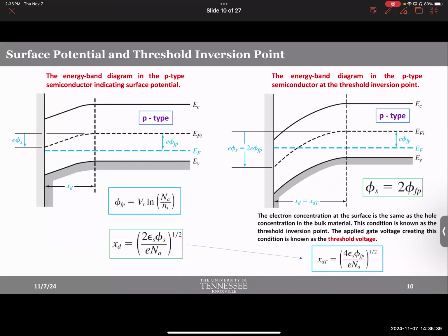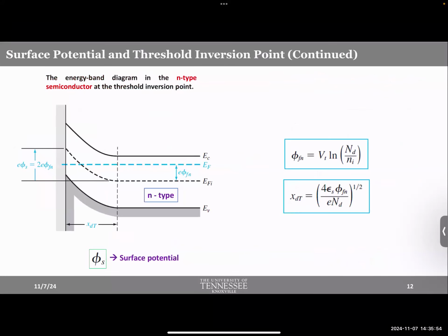This is where we stopped in the last class. We stopped at threshold voltage. And I told you, if there is one concept that we should take away from this lecture regarding MOSFET, it should be threshold voltage. It is that important. Threshold voltage is one of the parameters that we always use to tune circuits, and I will talk about that when I cover the concept of metal semiconductor work function difference in today's lecture. And I'll show you how that is useful.